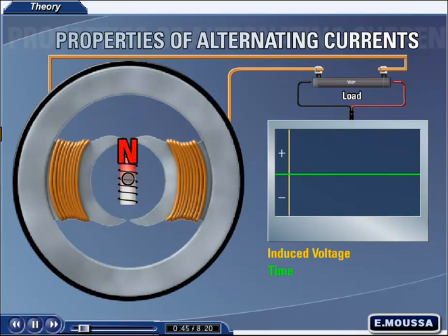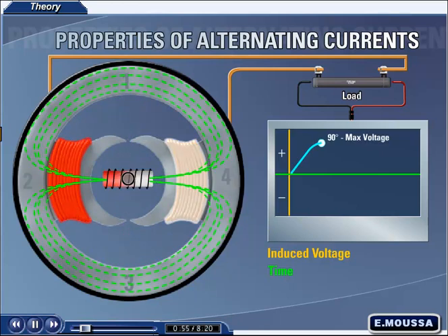We will use the north pole of the exciter as a reference. As DC current flows through the exciter's windings, a field is formed. As the exciter rotates counterclockwise from position 1 to position 2, the stator poles offer a lower resistance path for the exciter flux. As the exciter moves closer to the stator poles, more and more of the exciter's lines of flux will tend to flow through the lower resistance path of the stator poles.